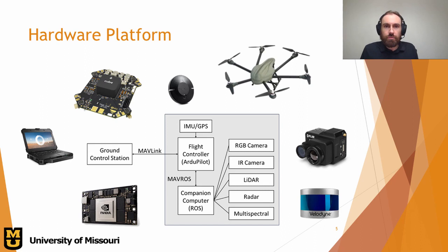All right, so one part of the Vader framework is the physical hardware. We wanted to build our own drone platform so that we could customize and configure it with all sorts of different sensors depending on the application requirements. Here we have a high-level overview of how the hardware components work together. The drone body consists of everything in the gray box, and it communicates with a ground station running on a laptop. We chose a hexacopter design based on the Sky Hero Spider 6, which gives enough flexibility to handle heavy payloads and long flight times.